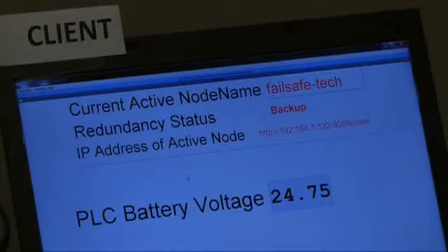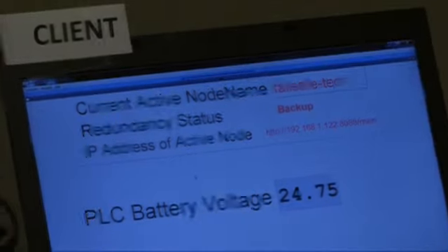And the way we have it set up is that once Universal Server fails on the master, we stop Ignition software on the master as well, and it has to be restarted by the operator. So we'll go ahead and show that happening at this point.